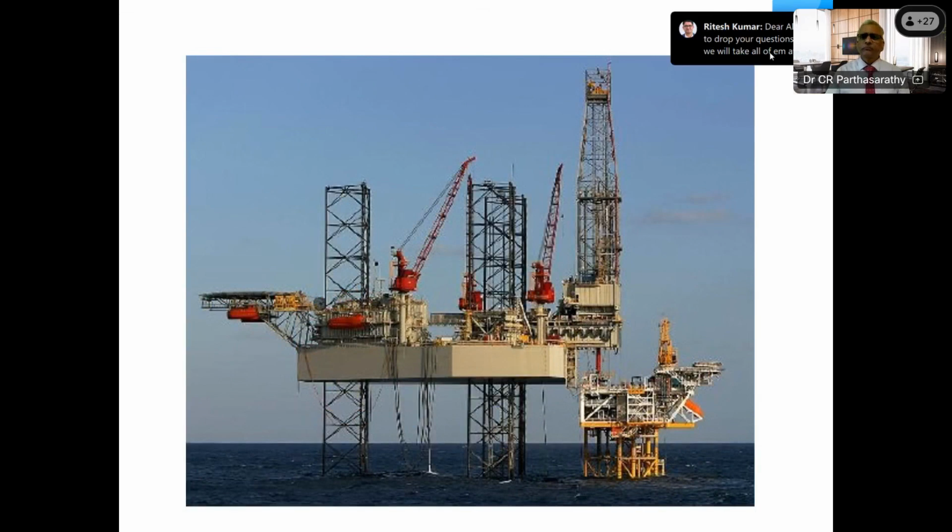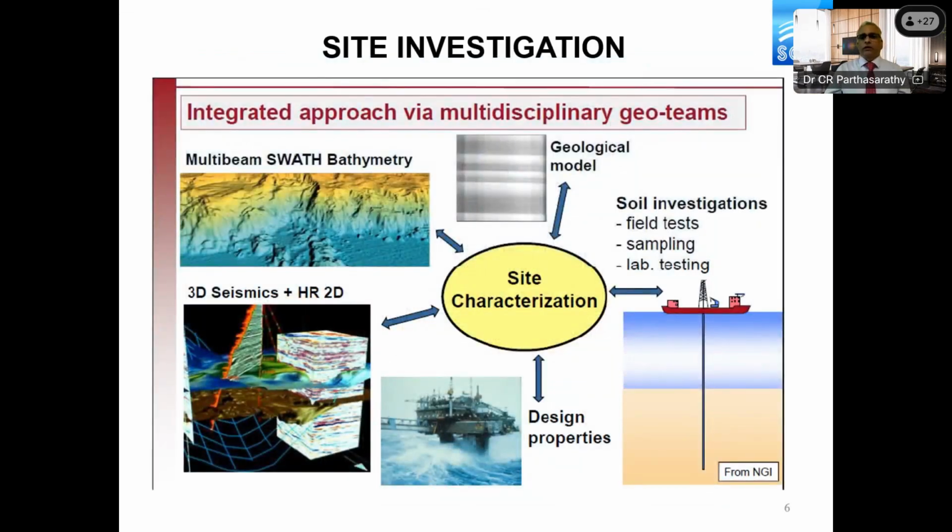And also the effect of this on the existing pile foundation is a soil structure interaction problem. You need to take care to assess if there are any precautions you have to take for the stability of the platform itself. So in order to proceed further with the assessment, we need to have an integrated approach of